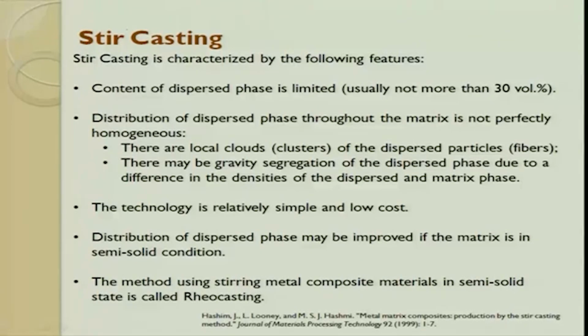Stir casting is characterized by the following features. The content of the dispersed phase is limited. Here you cannot go more than 30% volume fraction. You should keep that in mind.